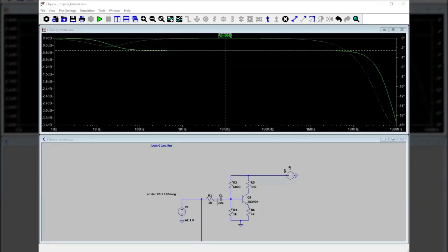So this is not matched. In fact, this is a 50 ohm source driving approximately an 800 ohm load. So there's not too much drop across this resistor. If this was matched, and that was 50 ohms looking in here, this would be minus 6 dBV here, indicating this voltage would be half a volt. This voltage is now about 0.95 volt, just for your information.